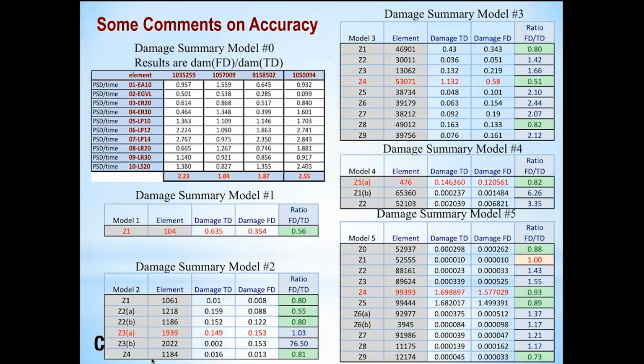to do the assessment. Now, there's an interesting observation about time and frequency domain calculations when you start from a time history. The frequency domain is accurate to up to half the sample rate. So if your sample rate is, let's say, 1,000 hertz, the frequency domain is accurate to 500. On the other hand, the time-based analysis is only accurate to between 10 and 20 times that highest frequency.